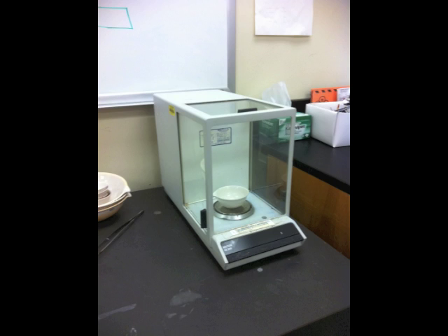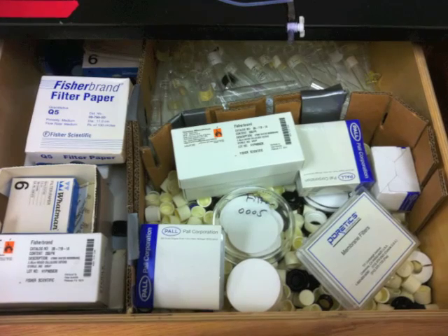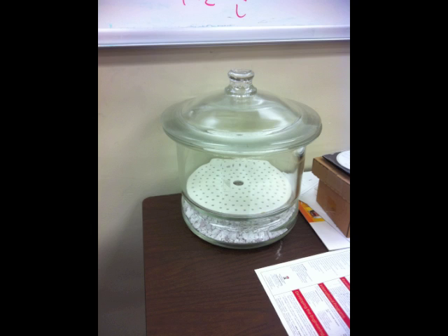Laboratory analysis. In order to meet the treatment goals, the composition of the feed water must first be characterized. This was achieved by performing lab analysis to determine the pH, alkalinity, hardness, solid analysis, and ion chromatography analysis, also known as IC analysis. From the experiments, a pH of 8.46 was found.